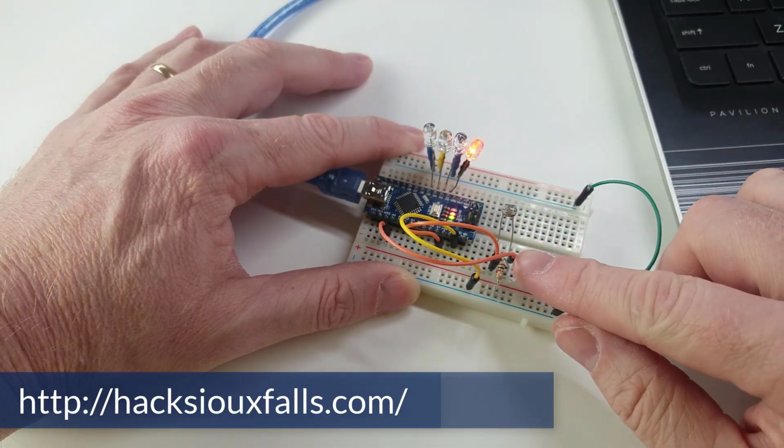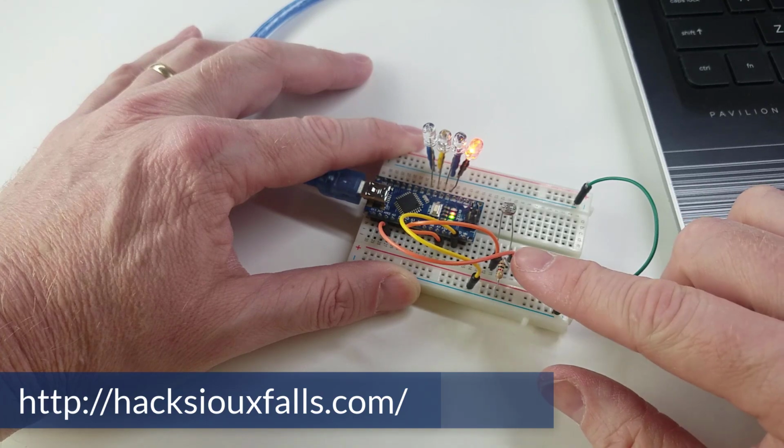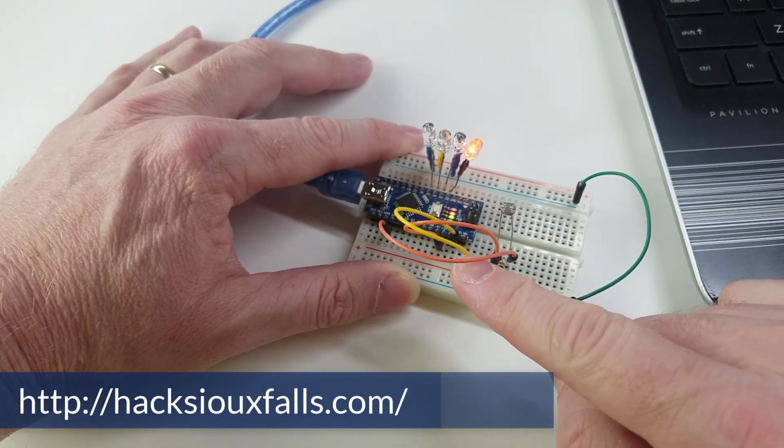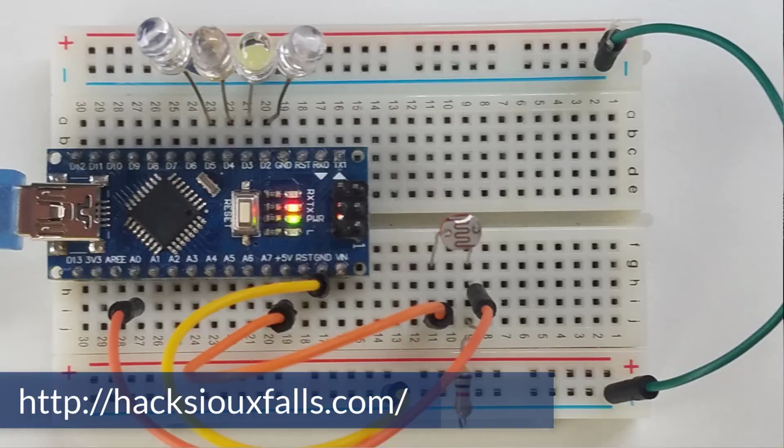So here's the final circuit. I've got a photoresistor here, and I've got a 1K resistor performing a voltage divider, and then this top orange wire is going over to our digital input, and just for display purposes I've put 4 LEDs on them. Now these LEDs already have resistors in them, that's why I don't have a separate resistor on those.